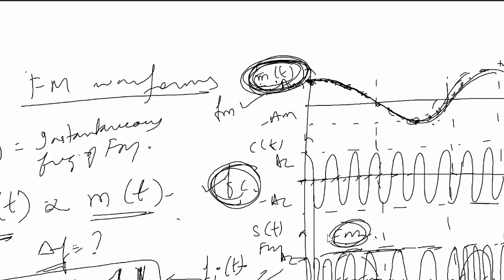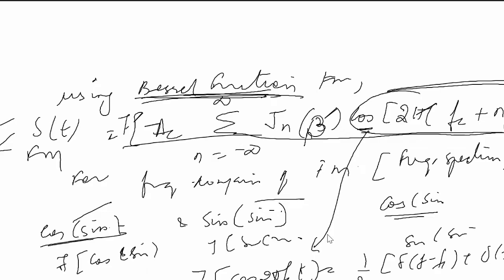It is the difference between the instantaneous frequency and the carrier frequency, because after frequency modulation has taken place, the frequency of carrier signal has changed with respect to message signal. That is the definition. The new frequency of the FM is referred to as fi(t), and the old frequency of the carrier is referred to as fc. What is the change between fi(t) and fc? That is called frequency deviation. So this is the concept of frequency deviation in FM, and all three equations we have already discussed.